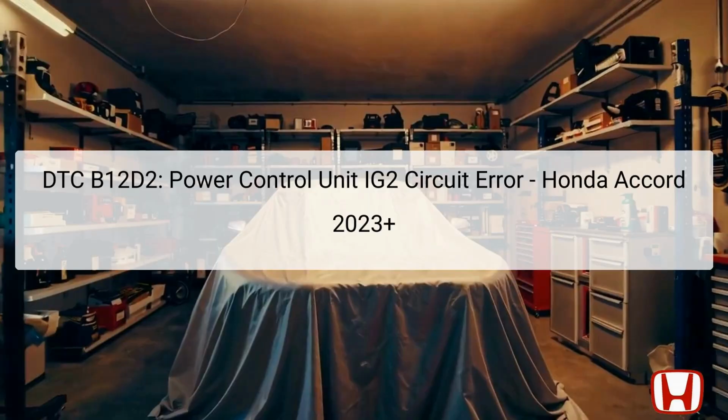The DTC B12D2 indicates a power control unit IG2 circuit error, specifically for the Honda Accord model from 2023 onwards. This error points to an issue where the body control module, or BCM, detects a discrepancy in the IG2 circuit compared to what the BCM identifies as the on state.